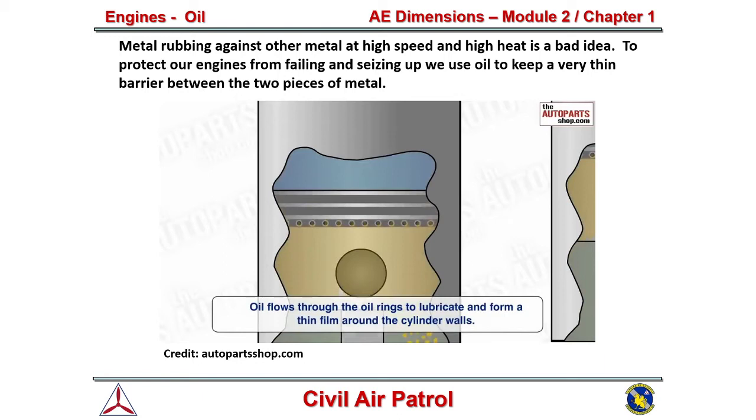And again, all the cylinders, the O-rings, it'll basically put some oil in all there. Now the O-rings, that's actually what the O-rings are doing. The O-rings are stopping the oil from mixing with the fuel. If you know me from Greenville, South Carolina, ask me about a runaway diesel detonation on an engine. We had an engine that we had a problem with. Oil was getting into the combustion chamber, and even though we turned off the engine, it kept running. We couldn't get the engine to turn off for about 10 or 15 minutes. It was very scary. But ask me that story if you know me personally. I'd love to tell it to you. All right, so that's oil. Okay.